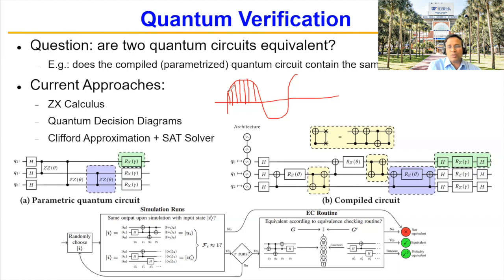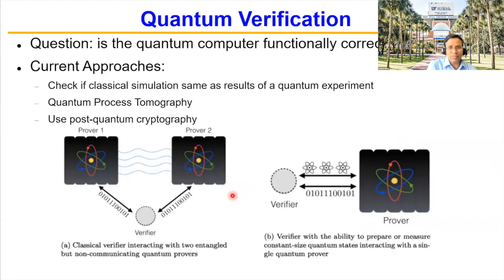You are looking at 0, 1 or whatever values at different time steps, because there are infinite time steps. So a completely correct answer, a model checker cannot do. The same analogy applies here. These qubits have a huge dimension to compare. Once you replace those gates using Clifford gates, suddenly it becomes much easier. Of course, you are abstracting, so you have to deal with false positives and false negatives. But now that you have Clifford gates, things are tractable in terms of different types of comparison, verification and testing. So that's the quantum verification problem.